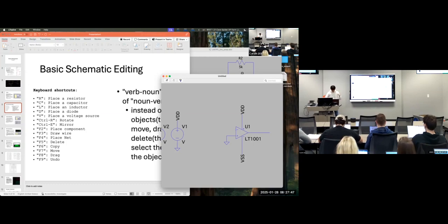Sure. I'm gonna go up to the negative terminal. Again, I'm gonna do F3 for wiring. And I'm gonna just do a little port right here, press escape. But now I'm gonna add a resistor, add 2 resistors, of course. So I'm gonna press R, and R brings up a little resistor graphic.